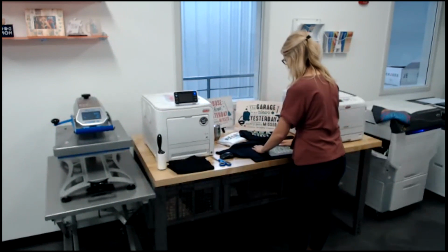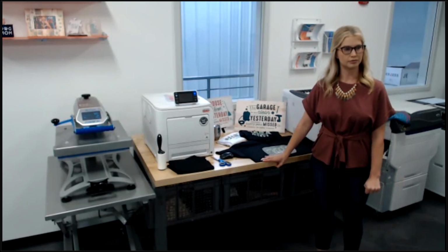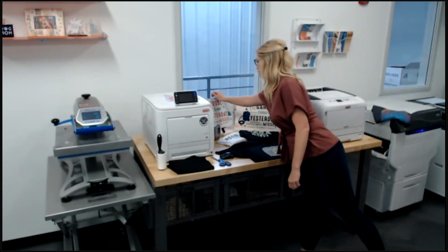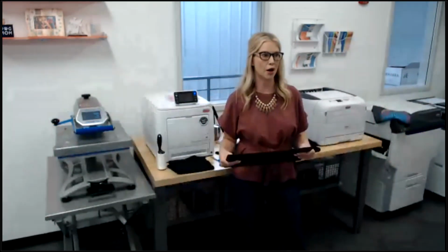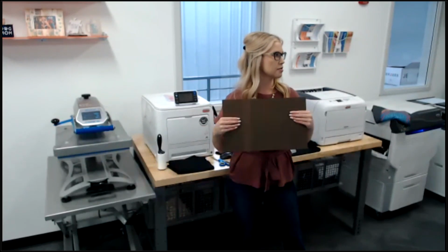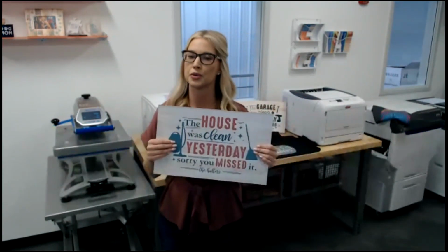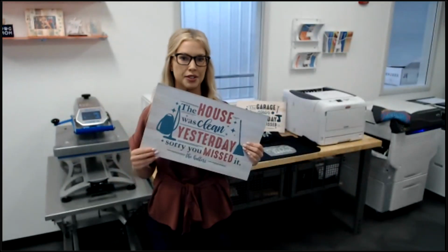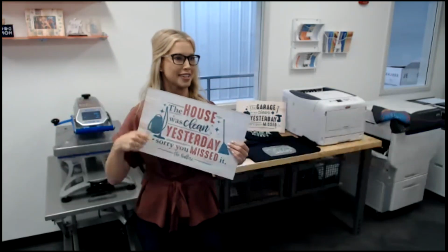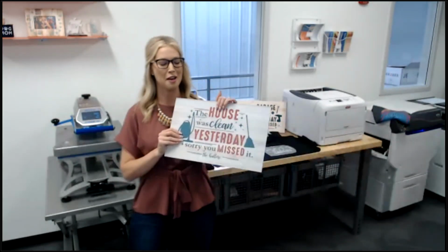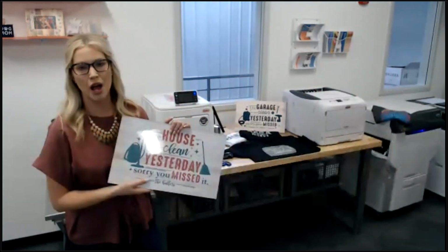We did have somebody say they wanted to make a puzzle out of a piece of wood and then laser cut it. Is there a particular process that they should use to do that? So what I would recommend is using the Unisub hardboard. This is a little thick though, or maybe even some MDF, because you can sublimate right on this. What I would do is I would cut it out first and then sublimate. Make sure you leave the masking on though, and then you'd have to demask and press. So that's definitely an option that you can do.